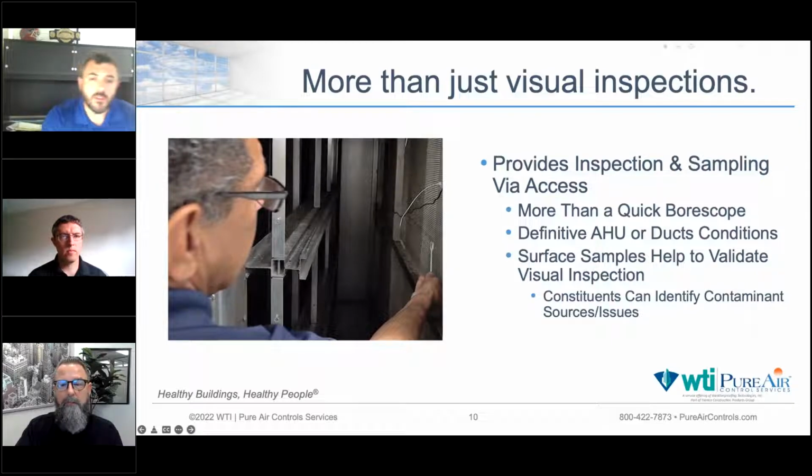So you can go on, but the point is that performance data, referring to the types of testing that a test and balance technician would do on an air handler, are really valuable because you really understand how that unit is actually performing. And if you have the design data from when it was originally installed, whether it was 10 years ago or 40 years ago, you can compare it against the design. But even if you don't, you at least have an idea of how it's actually running, using the laws of physics to give you true data about those kinds of scenarios.